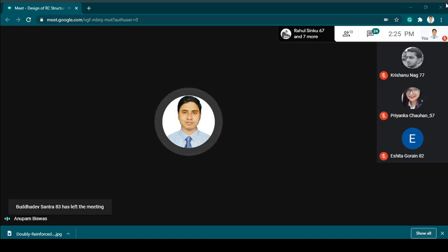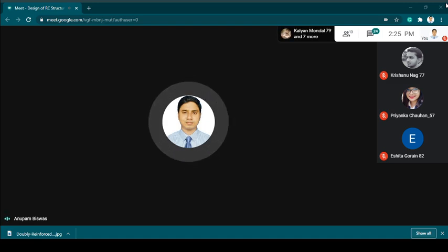The beam is reinforced with two numbers 18 mm dia bars and two numbers 20 mm dia on the tension zone. Read it as dia, it changed by autocorrection. Then the compression bars are placed at a distance of 40 mm from the top, and use M20 and Fe415 steel.